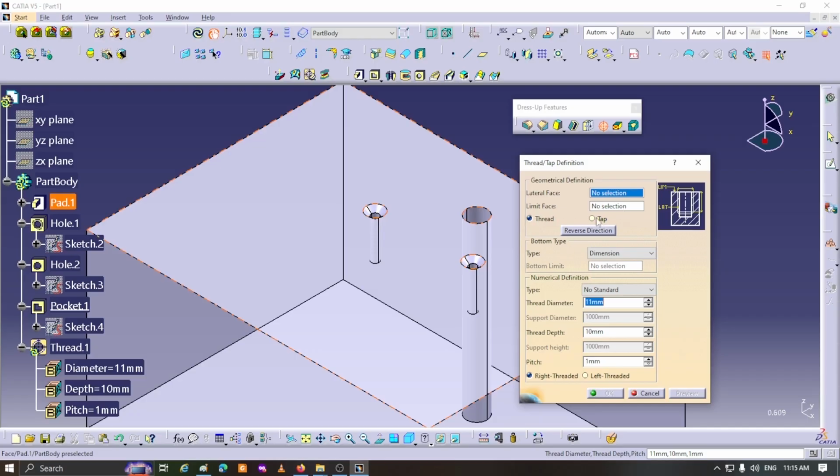You can of course change the check mark if needed, but if you make a wrong choice, you'll definitely get an error. On the right side, you'll see a preview image. This image changes based on whether you're working on a hole or a shaft. The adjustable parameters on the preview image are highlighted in yellow.